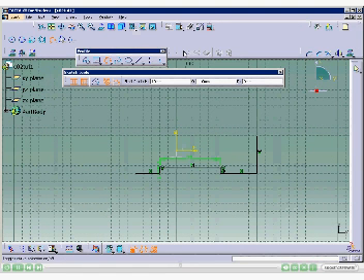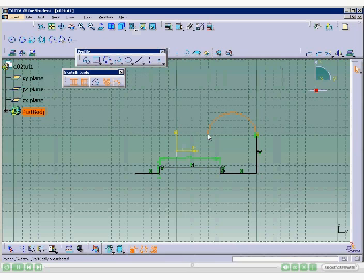Select the start point of the arc as the end point of the previous vertical line and click on it. Move the cursor to a point whose coordinates are 70 mm, 50 mm. Move the cursor to specify the third point of the arc. Click on the point when the cursor snaps to a location 40 mm, 20 mm, in the geometry area. The coordinate values are displayed on top of the cursor. This draws the arc for the after loop.